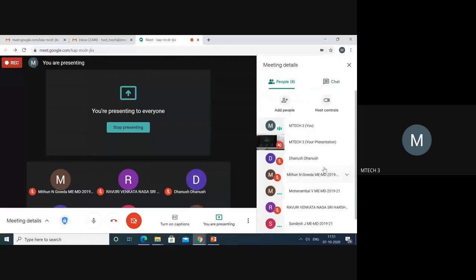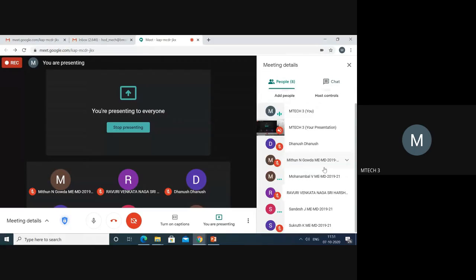Now, what we have done today is, to start with, we have discussed the concept of the Hall effect sensor. We have discussed the Hall effect sensor, which is nothing but what type of sensor? Hall effect is a magnetic sensor. Okay, so after the magnetic sensor, we understood the working principle of that. Then we went to what is called the proximity sensor.